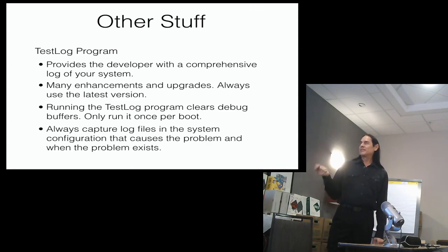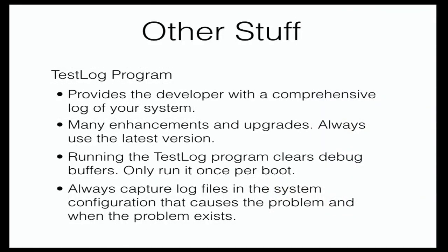This is the other thing, and it's pretty important. You can't have a problem, reboot your system, and run a test log file when the problem doesn't exist. You've got to capture the data when the problem is happening, not after you've reset and rebooted. Sometimes you can't do that, if it hangs the system.